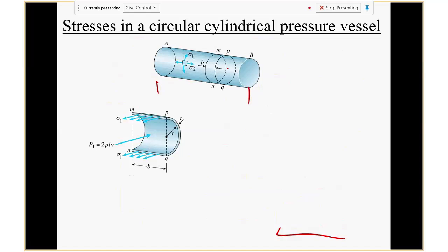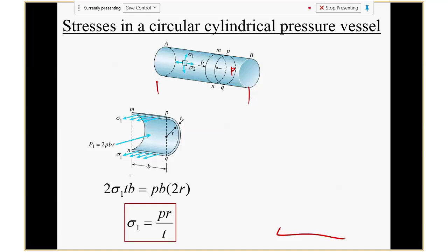There is a pressure P inside. Can you find the circumferential stress? We just talked about it. You can make the cut as shown here, and you're going to have this equation, which we already showed. Now, for a container like a Coke can, imagine a can of Coke with pressure built up inside. Circumferentially, you're going to have this much stress.